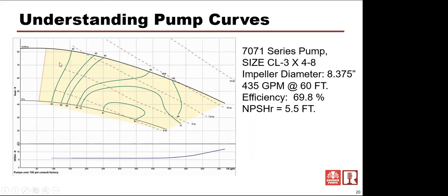Impeller. If we were to look at this curve, you're going to see dashed lines coming down here. These are horsepower load lines. If you were to have a pump with this size impeller and it was running here, you would know that this is consuming somewhere around 7.5 horsepower with water at that particular point. All of these curves are rated in water. If we were to run farther out on the curve, in other words less resistance, more flow, we get out here somewhere around 475 gallons a minute at about 55 or 56 foot of head.